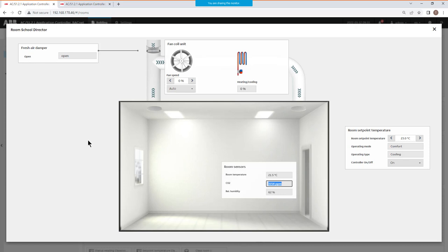So now I go down to the level below 2500. Now it's only 1600, and my training board was clicking right now. The relay was operated, and you see here on the upper left side, closed.